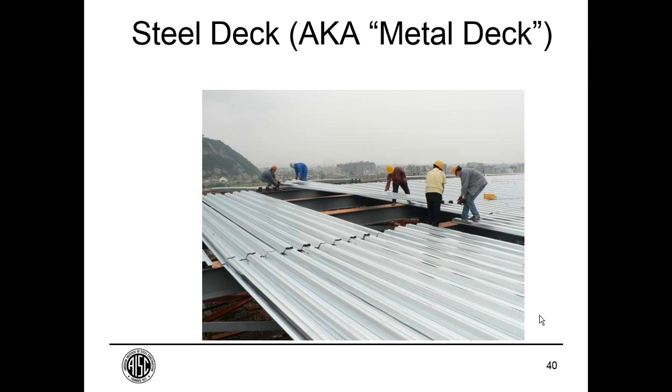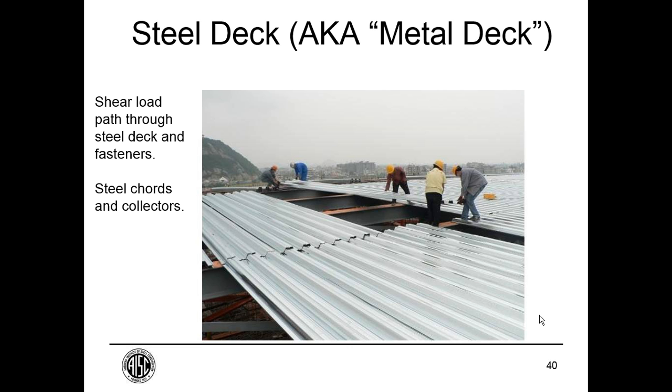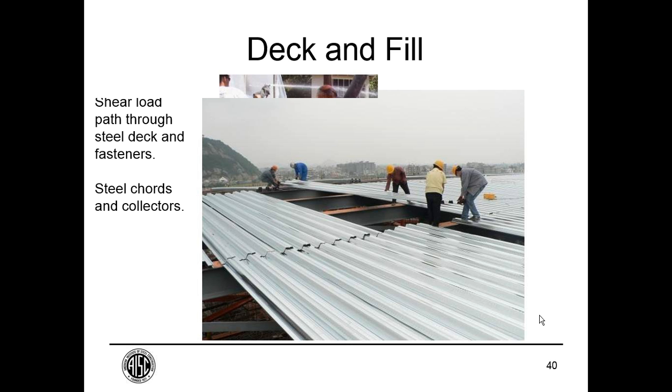Diaphragms. We'll talk about different types of diaphragms and then the roles of diaphragms. Common diaphragm is just a steel deck that is either welded to steel framing or connected with screws or shot pins. The shear is handled in the deck, and then the chord and collector forces are in the steel members.